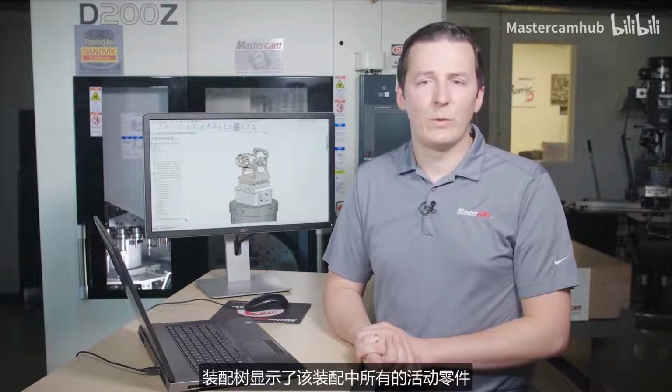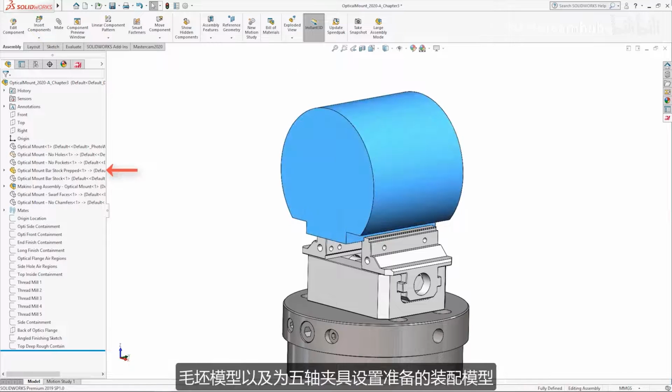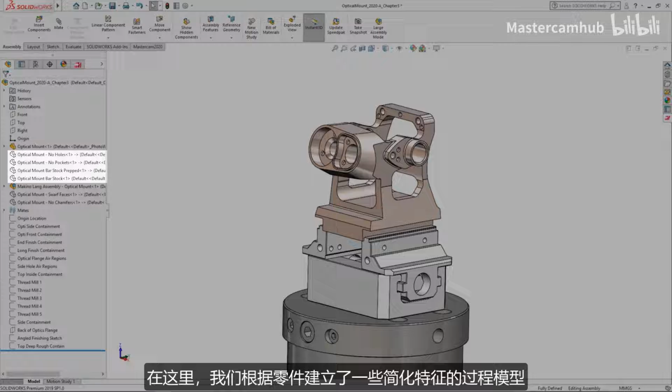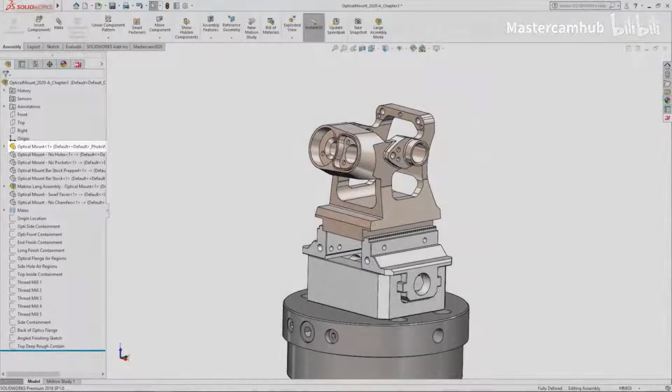Mastercam for SolidWorks takes full advantage of SolidWorks assembly files. The assembly tree shows all the individual components that are active within this assembly: the finished part file, some defeatured models used to simplify the programming process, the prepared stock, and a subassembly for the 5-axis fixture setup. Here, the defeatured models are created from part copies, which reference the finished part file.